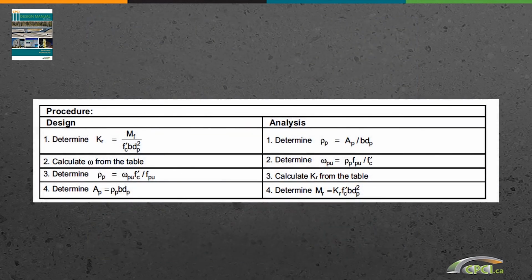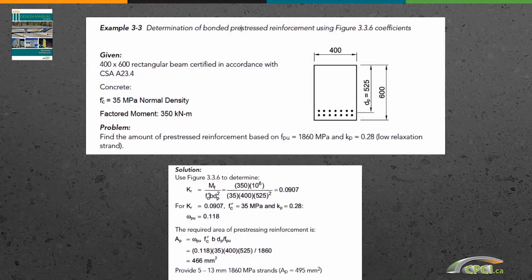These are the formulae that we used for the stadia element because it's a pre-stressed precast. Therefore, these formulae here pertain to a pre-stressed element. That's why we have the A sub P here as opposed to A sub S. And these are the introduction formulae for the table that we have in the book. And another fast example of a section using the same tables, but this time it's not a stadia, it's a typical rectangular section.